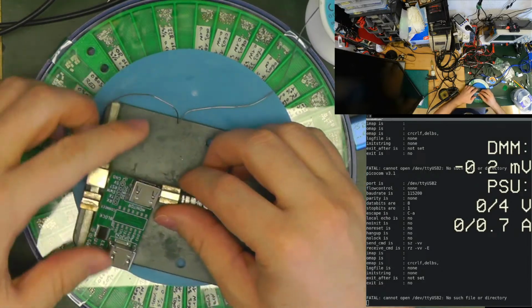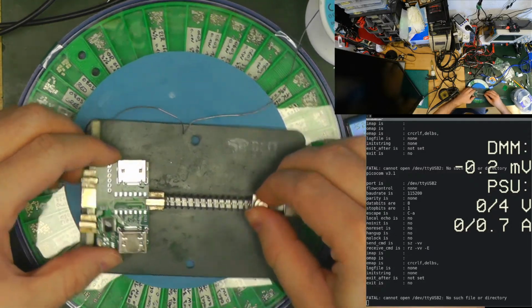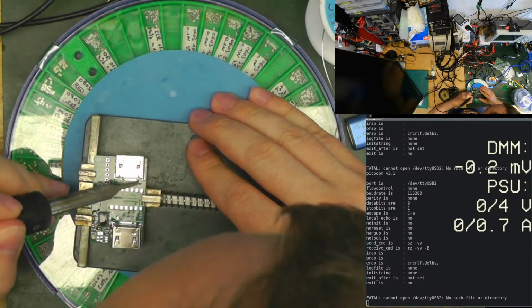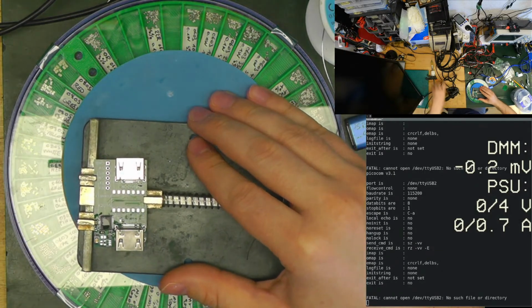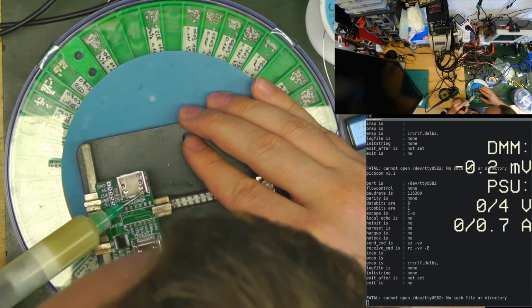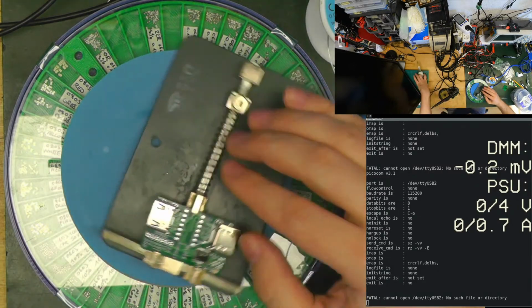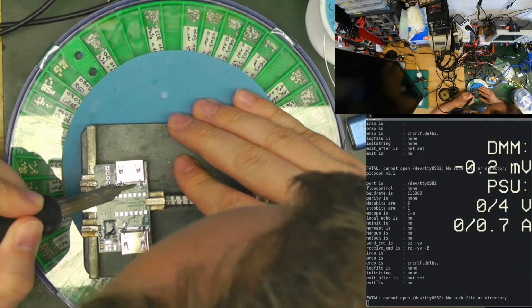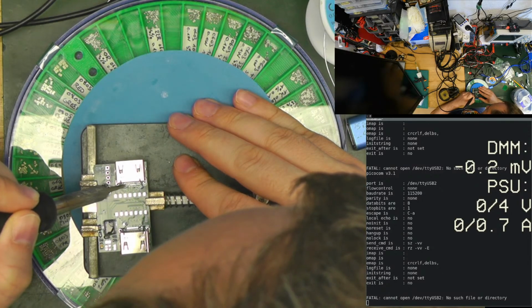We can solder the front pins, and it is still aligned. Yeah, it's still aligned. There should be enough solder. Maybe there's enough solder. Needs a lot more flux. These pins are super hard to solder. Not sure why, they shouldn't be corroded because they're not that old. Okay, with flux it makes it easier.